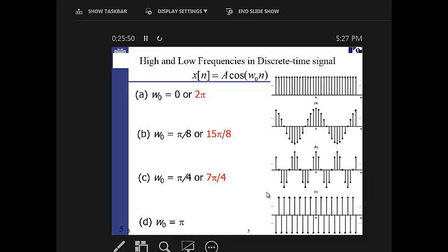So in the time domain, when we say that x of t is a signal, for example, a cosine of omega t plus some initial phase, which is mostly represented by phi sub 0 or something like that, or a constant value. Here, this omega, which normally in the analog case, for those who are studying telecommunication, is shown with this Latin omega, can change from 0 to infinity. And the signal here is a cosine signal with a previously known omega.